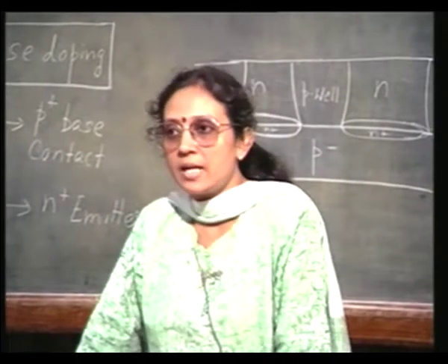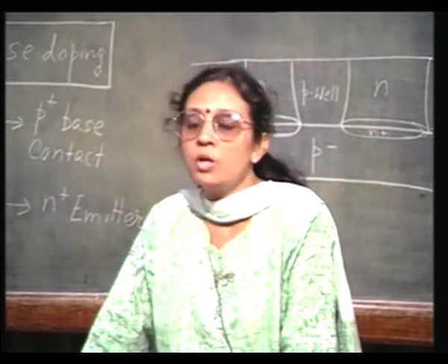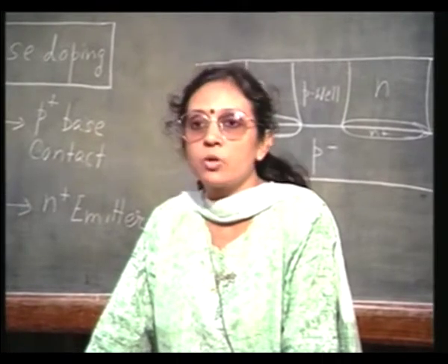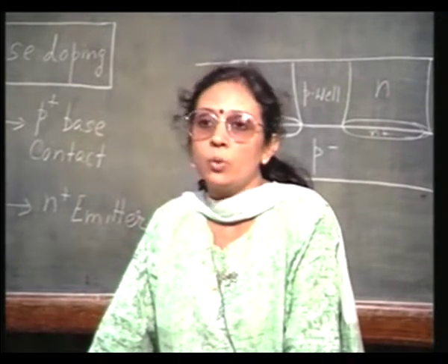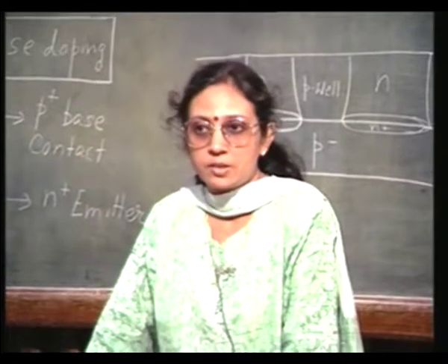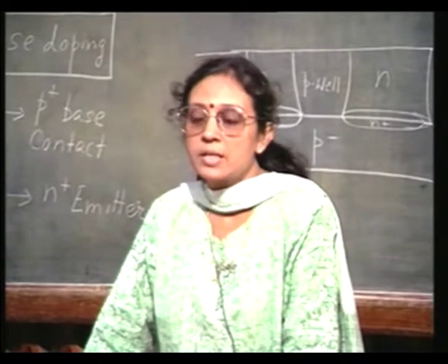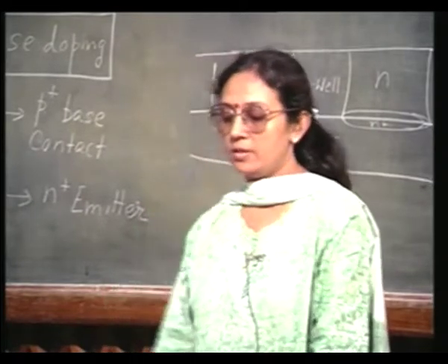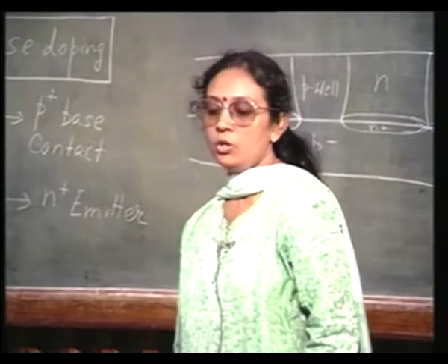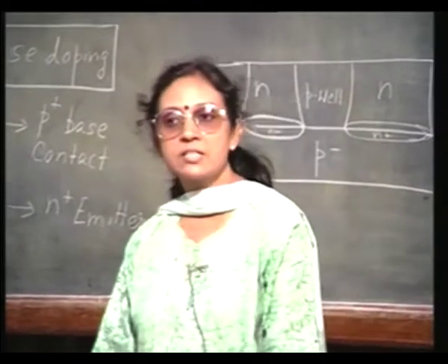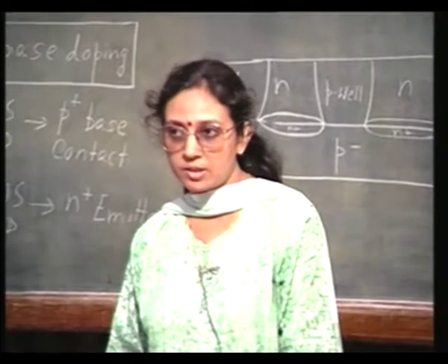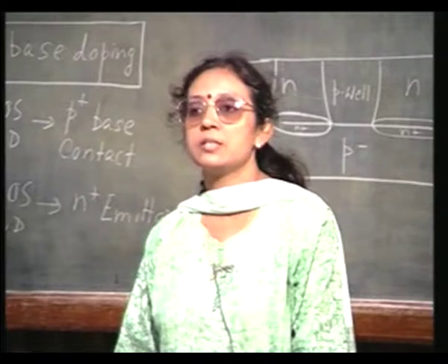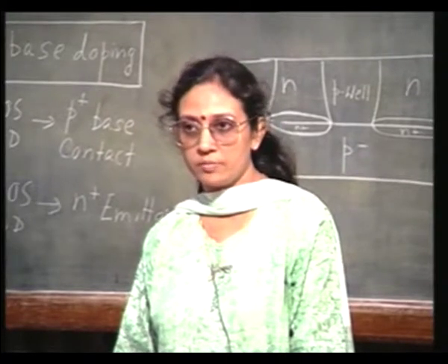First of all, let us have polyemitter transistors. You know, for ECL logic we use high speed transistors, and whenever we talk about high speed transistors we want polyemitter transistors, right. Polyemitter transistors have much higher gain. Okay. So, the gate in the CMOS transistor can be used to define the emitter region of the bipolar junction transistor, right.